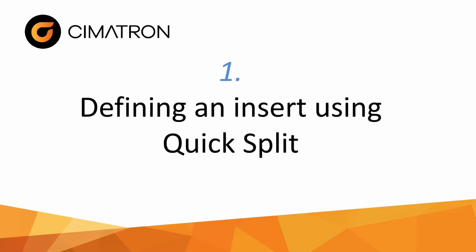The first insert option that we'll look at may be an obvious one, but let's not forget that while you are splitting your part, you can divide it up into as many groups as you want to. And each of these separate groups of part surfaces will get exported to its own mold component, which means Quick Split is actually a great tool for defining mold inserts.